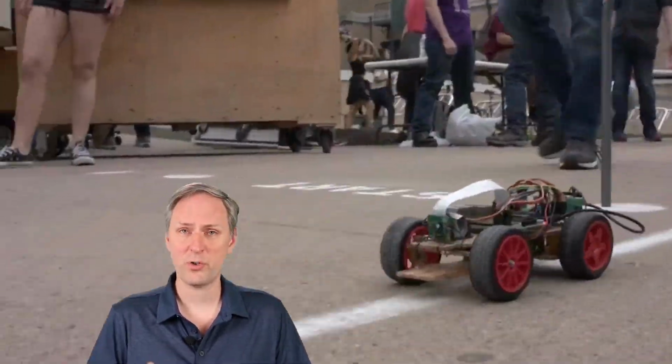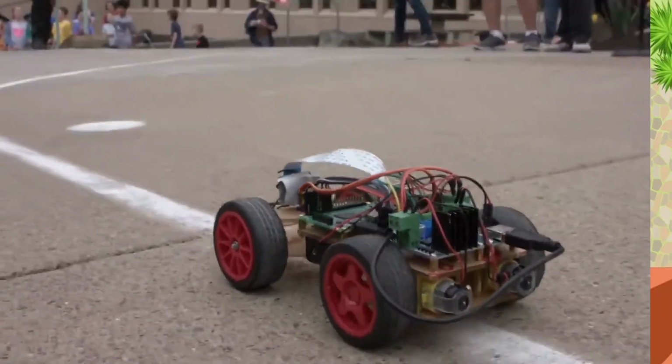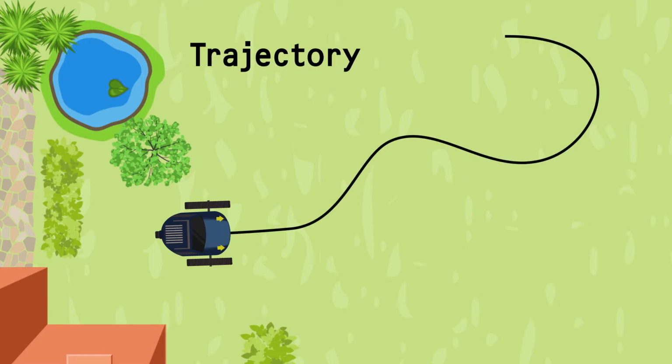You want the robot to control the steering, but to do that, it must know what path it is supposed to be following. In robotics, we usually call this path a trajectory, and it defines everything we need to know about the robot's desired positions and speeds. The trajectory consists of a sequence of points, commonly called waypoints.